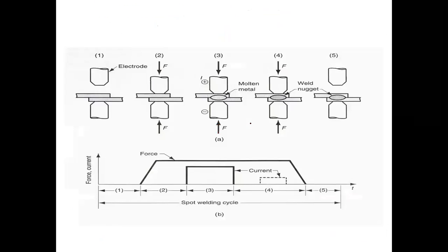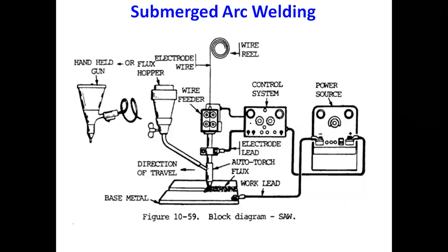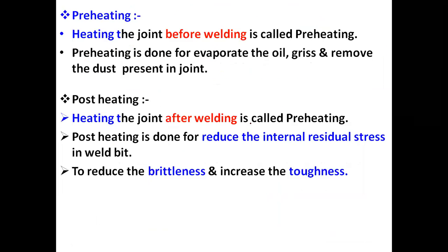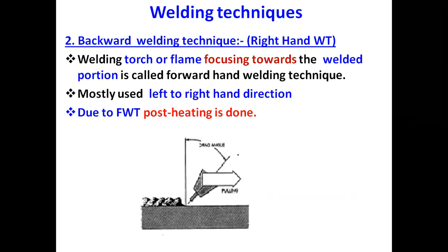If a crack is present in a welded joint, then the welded joint becomes weak. These welding cracks are caused by low ductility of weld and base metals combined with high restraint during contraction. This is the first defect.